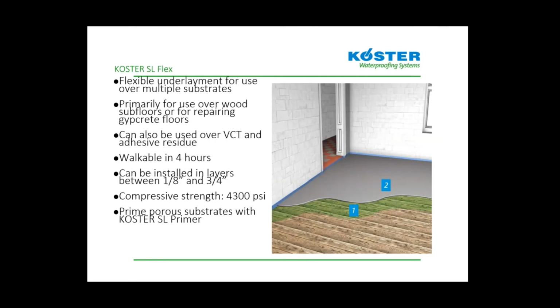The SL Flex is another kind of niche product. This is a flexible underlayment for use over multiple substrates. Primarily, it's used for repairing broken gypcrete floors or old wood subfloors. It can also be used over most kinds of adhesive residue, and over VCT. This product is also walkable in 4 hours. It can be installed as thin as 1/8 of an inch up to 3/4 of an inch with normal spacing,